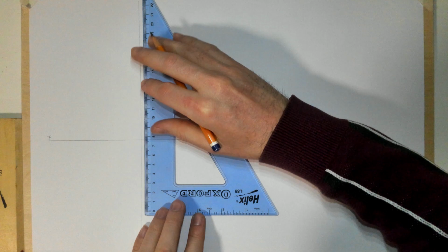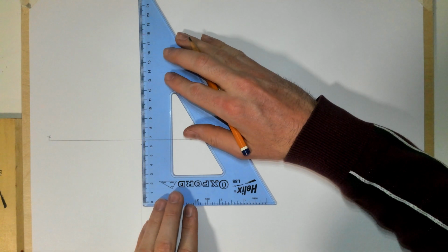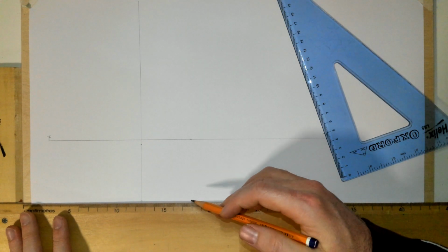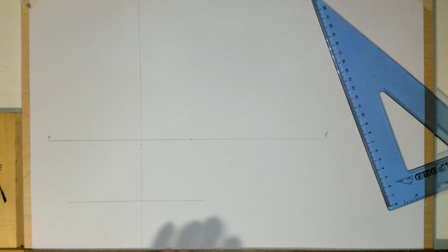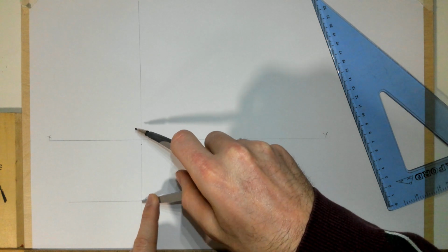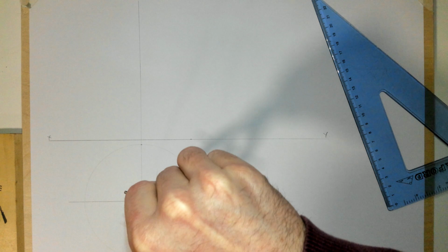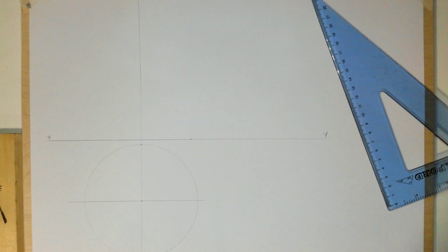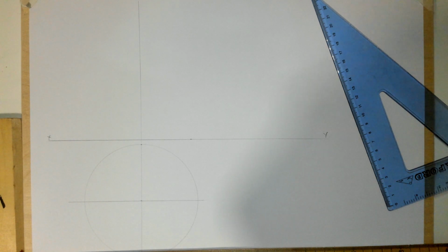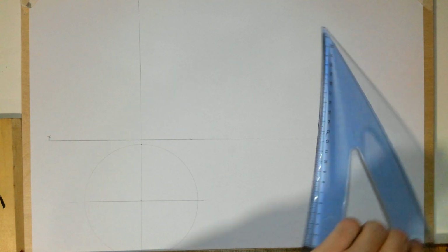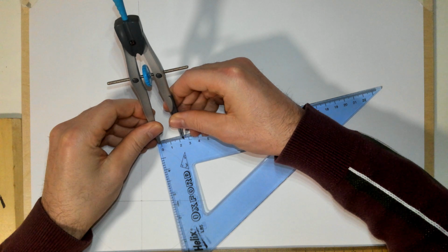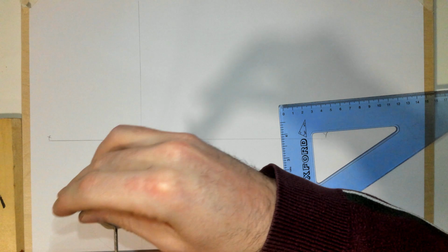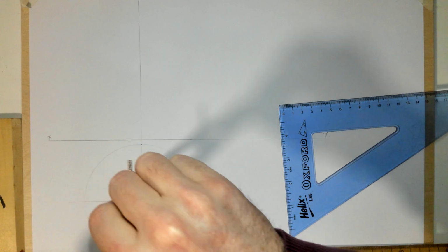And the diameter of the big circle there is 12 meters. So I'll leave a gap of about 5 will be fine. And then 12, so that'll be 60 millimeters down. Draw my center axis across. Now, draw in that radius 60. Okay, and then the throat circle in this case, they tell us is diameter 5 meters, which is 50. So that's radius 25. Okay, so drawing your throat circle there as well.